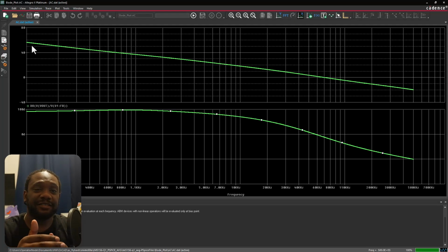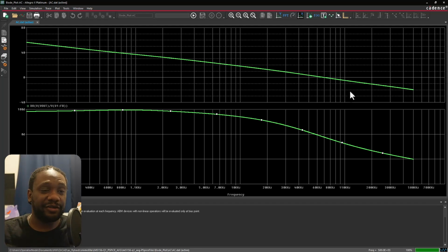Because that switch being on longer is going to increase our output, or increase the amount of energy that we dump into the primary side inductor, which gets stored in there, and then it gets released to the secondary side inductor once the switch is turned off. Okay, and then that gets released and whatnot. So now that's the gain response. Notice how it starts to go down to 0 dB, meaning a gain of 1 essentially, and decreases further.